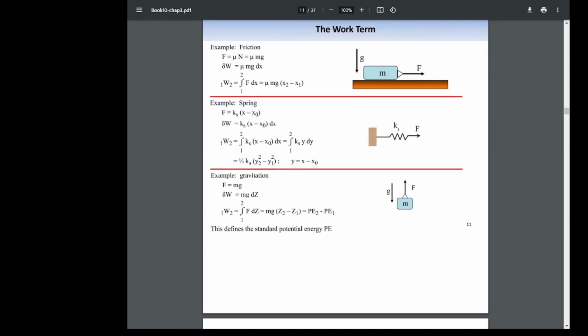The next is spring. And we're starting off with, like, this is our initial unstretched length. And then the difference between these two, so x would be our initial one minus however much you stretched it, either compressed it or stretched it from that initial length. This is our delta x, essentially. Okay, we could do the same things as before. We have our incremental component of work is just equal to the spring constant times that difference times our little incremental